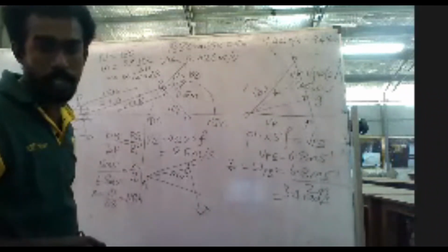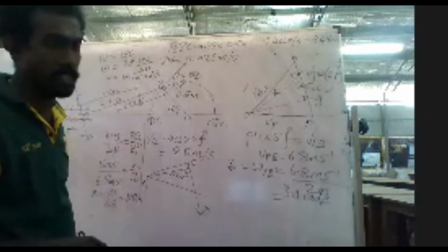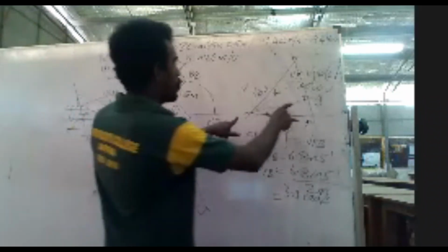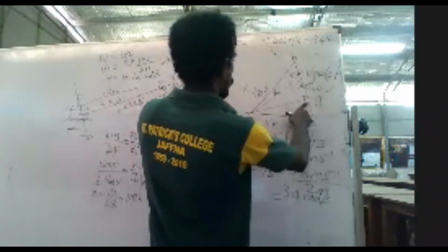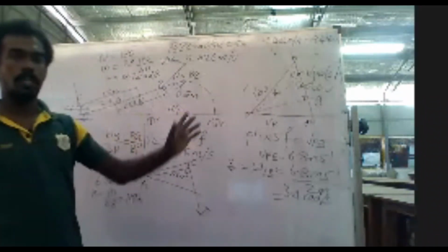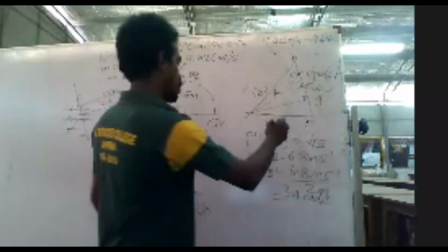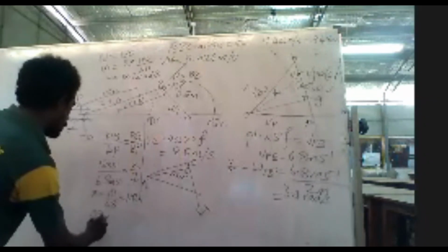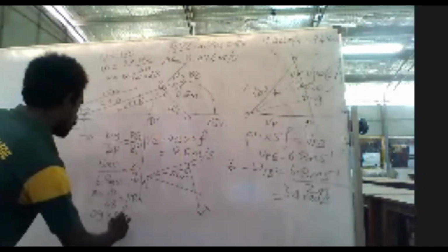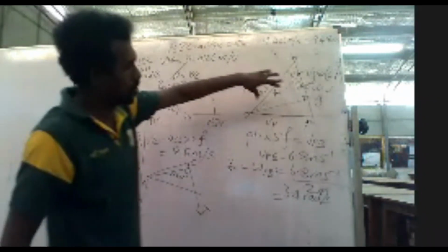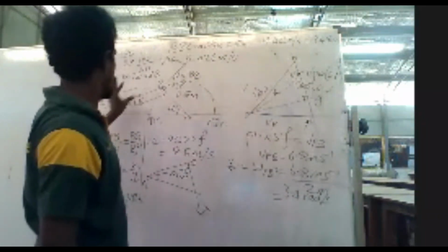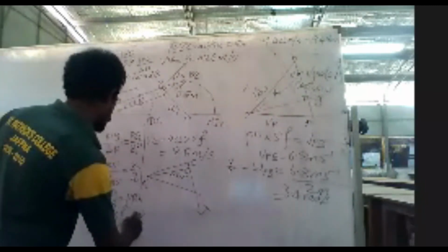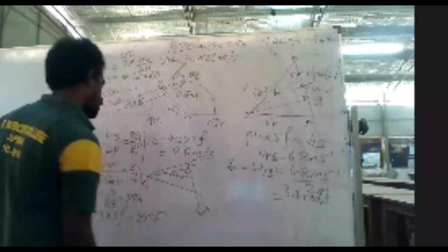By measurement, we find the linear velocity of point P, that is Vg, vector OG, that is 8, right? So we now can find the velocity of this, that is measurement of OG into the scale factor, right? So OG into my scale factor will give you the velocity of this point G. That's equal to 8 meter per second, right?